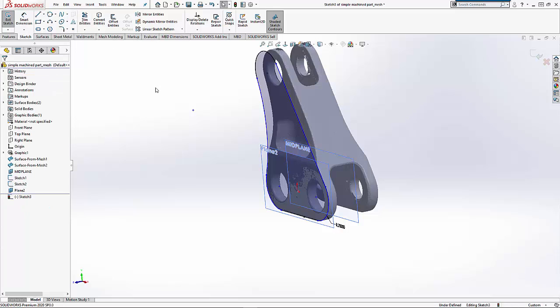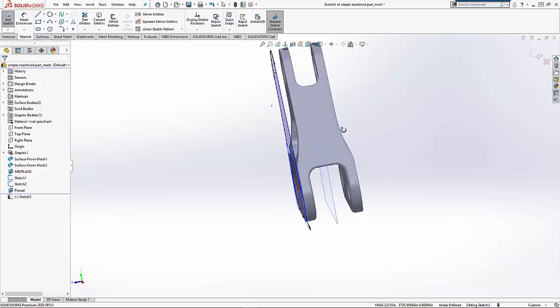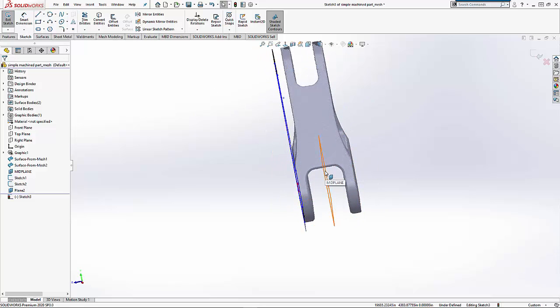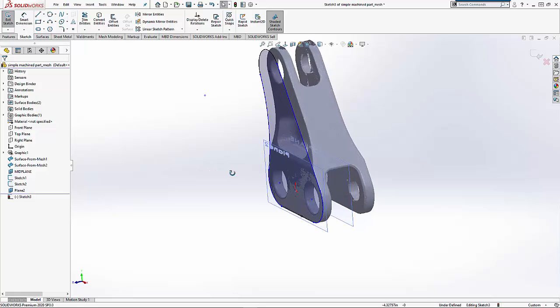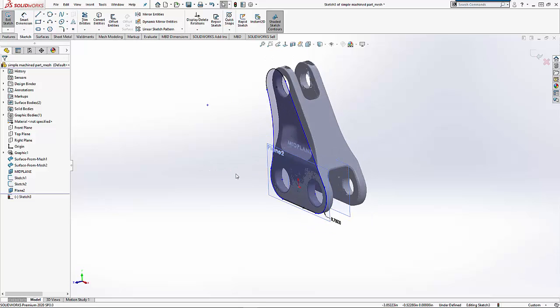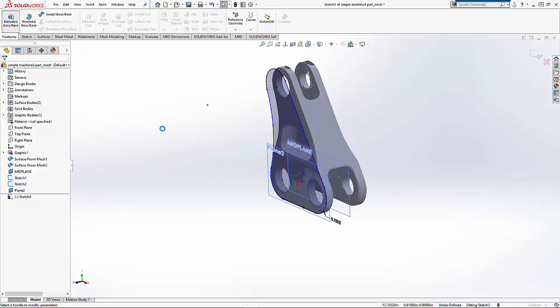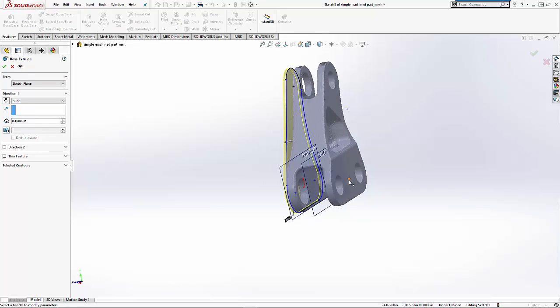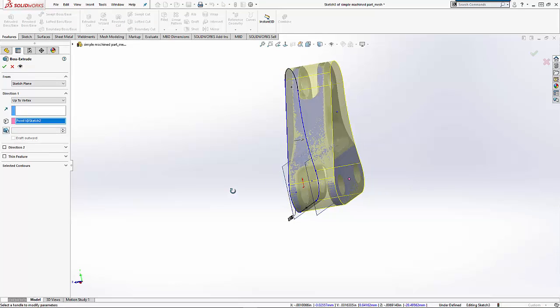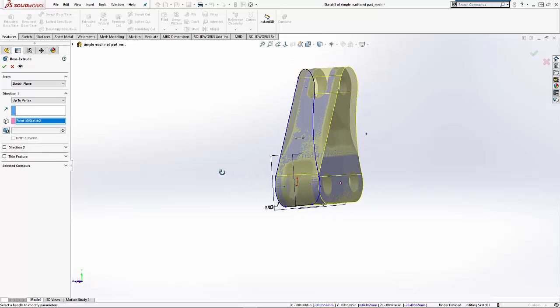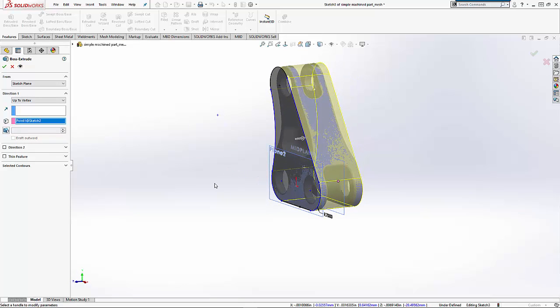Now, I drew this out on the outer surface so I could extrude it over to the other side. Sometimes we might want to take advantage of symmetry, so I could have started sketching on this mid-plane. The problem is with the mid-plane extrusion, the only option I have is a distance. Here with a sketch out on this side, if I extrude it, I can actually use an up to vertex end condition and generate that original shape this way.